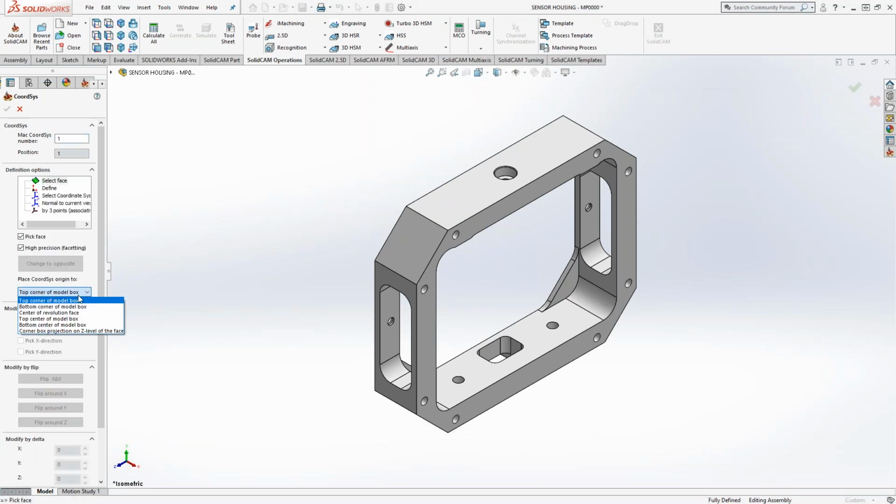Basically, top corner, bottom corner, it's going to approximate off of your target solid what the shape of the eventual stock will be. More often than not, it's either some sort of cylindrical billet, some sort of bar stock, or in the case of milling, it's some sort of box: length, width, and height. So that's why top corner, top center, bottom center, all those make sense in that respect. We don't have a solid model to work off of for your stock. We're working off the target model.